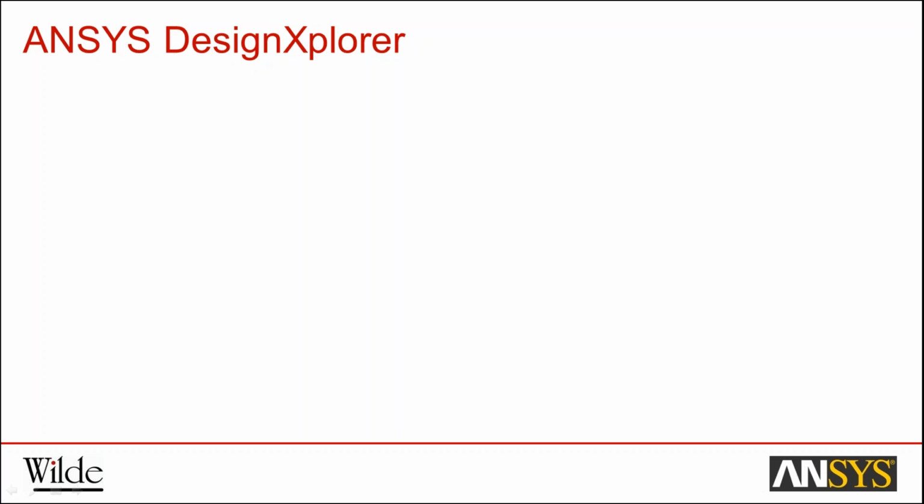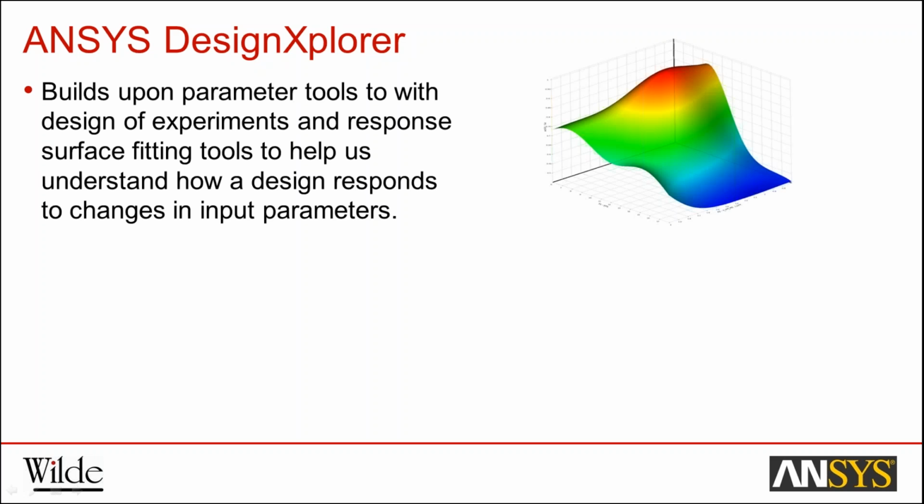Design Explorer, now, this is a very powerful tool. This is included at the Mechanical Enterprise level. And it builds upon the parameters tools that you'll have in your Mechanical license. So with parameters, we typically define input-output parameters. Input parameters are typically things like CAD dimensions, so dimensions of parts, thicknesses, holes, for example. Output parameters are typically things like stress levels, deformation, component mass.